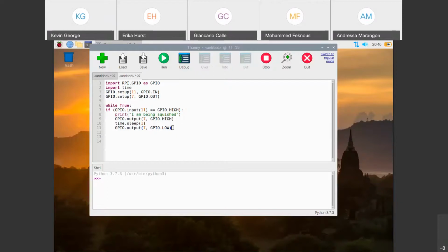So you'll notice on your sensor, there's 3 pins. There's a positive, there's an out, and there's a negative. So how we're going to do this is that, ideally, we're going to use the female to male wires that came in the kit because that's going to be the easiest to wire up with. So I'm going to do that on my own here.